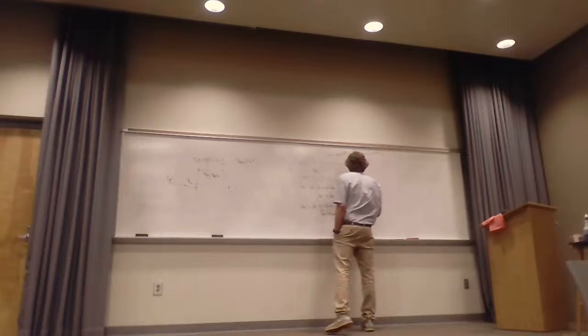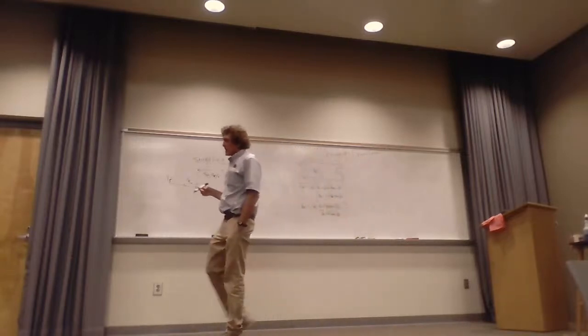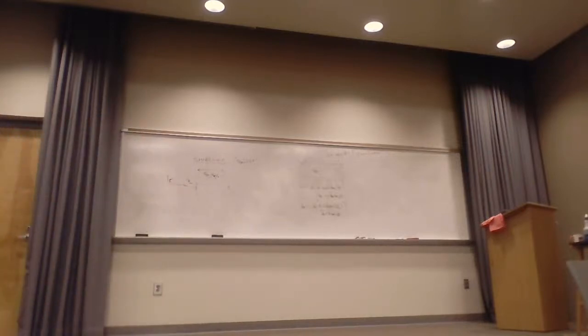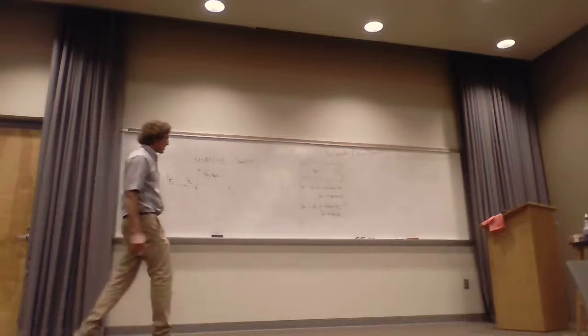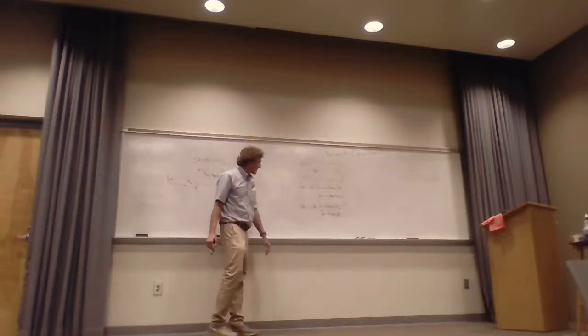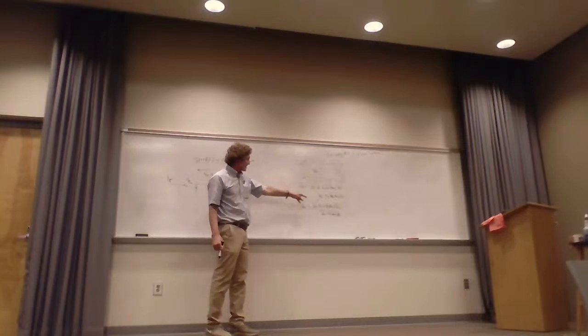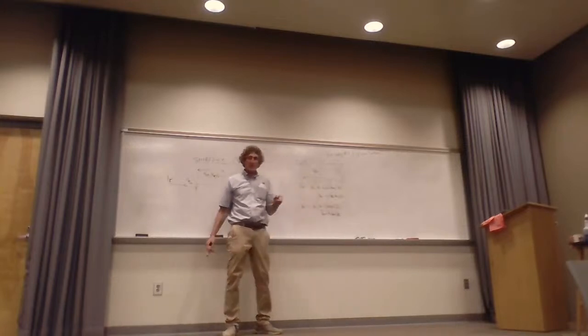And you don't have to know that, but that's the formula, where R prime, L prime, G prime and C prime are the resistance, inductance, conductance and capacitance per meter. Y'all remember that? All right, you don't have to worry about that. But what I need to do is draw a parallel between this guy right here and this guy here. Now you can see that this guy right here is lossless, this is lossy. It doesn't have the j and it's got a hyperbolic tangent.